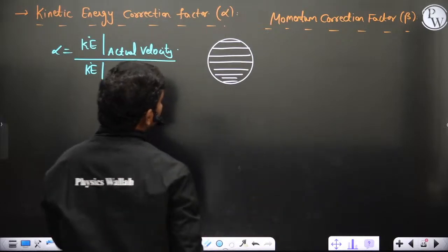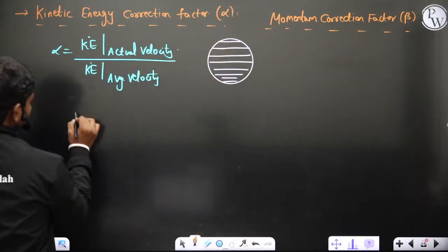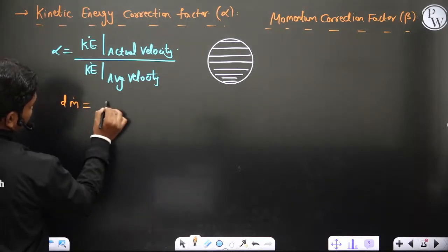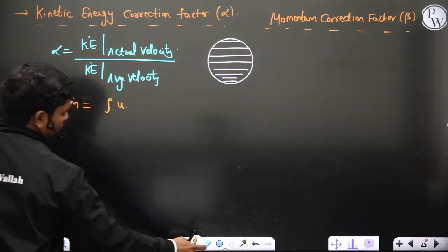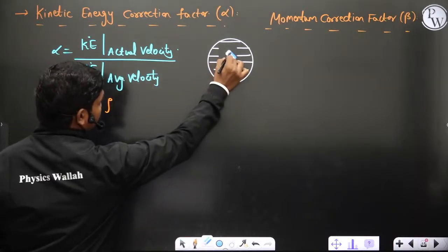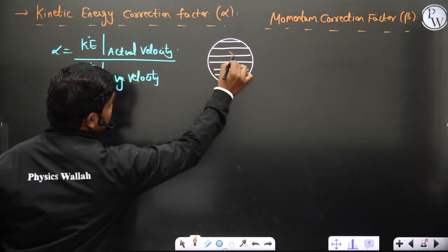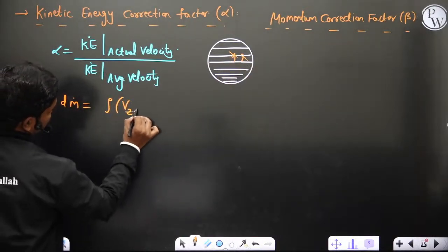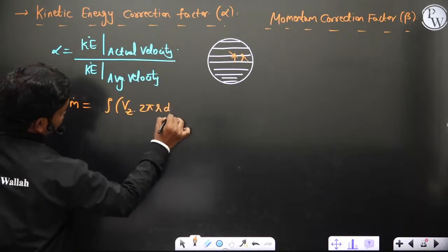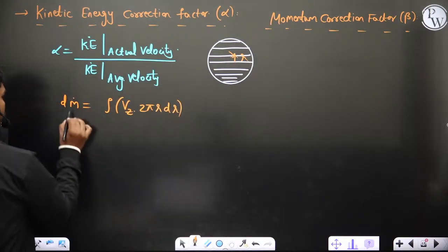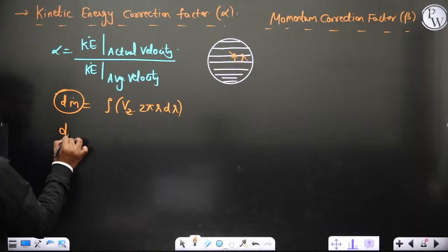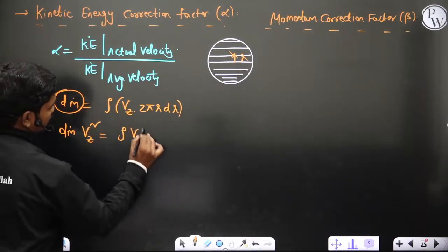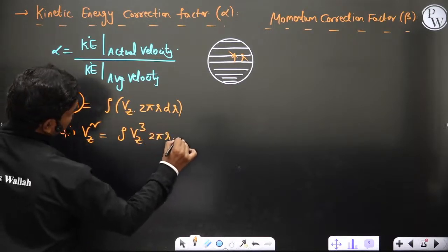Then through this cross section, whatever is the discharge, d m dot, is equal to rho u or v. Let us suppose at this radius r, it is rho into vz into 2 pi r dr, which is the actual flow. Now if you want the kinetic energy of this particular part, dm into vz square, this gives you rho vz cube 2 pi r dr actually.